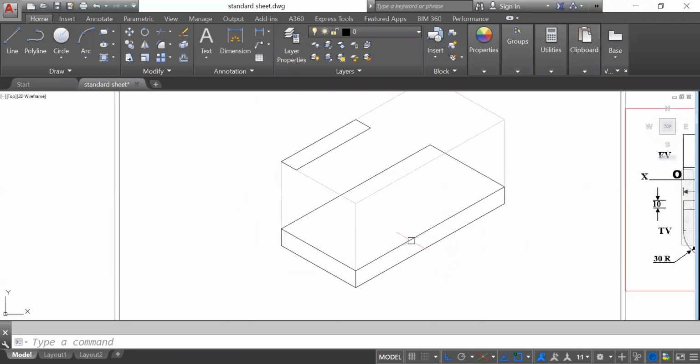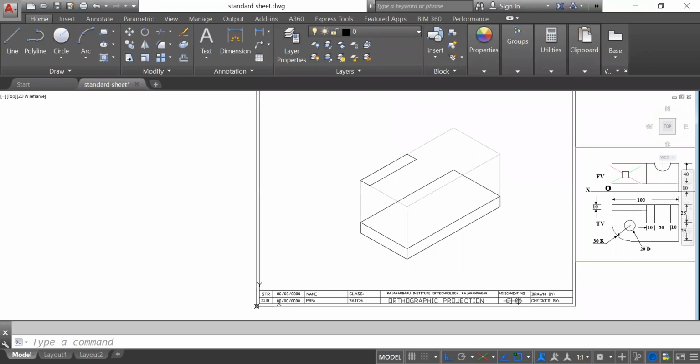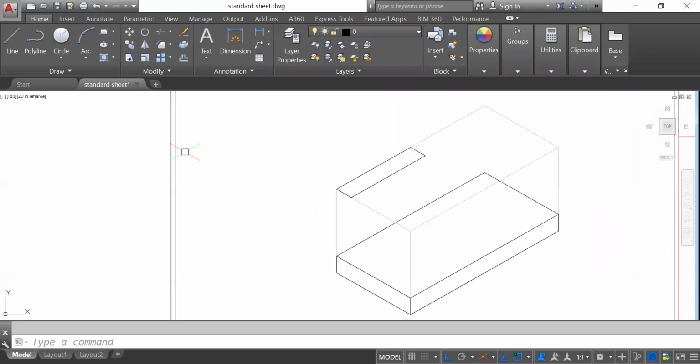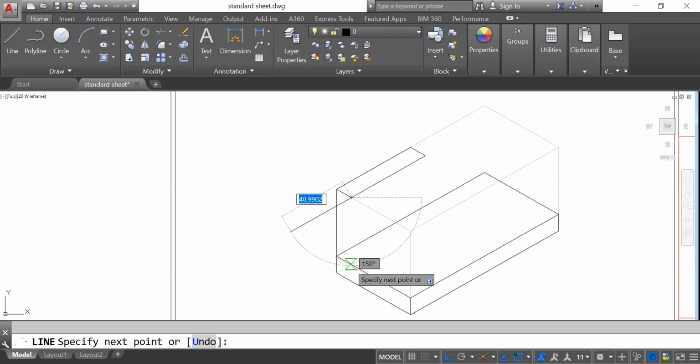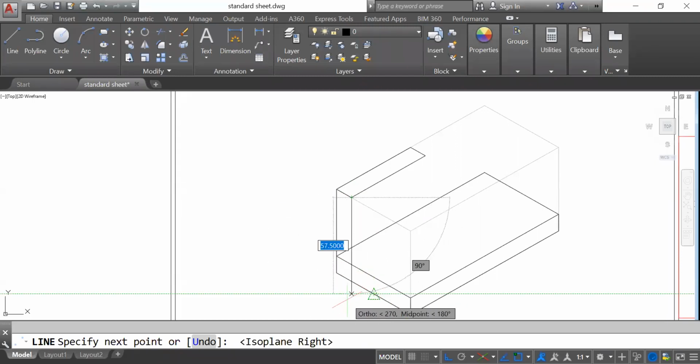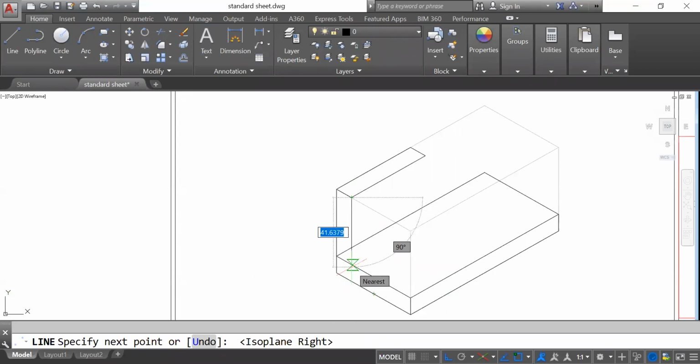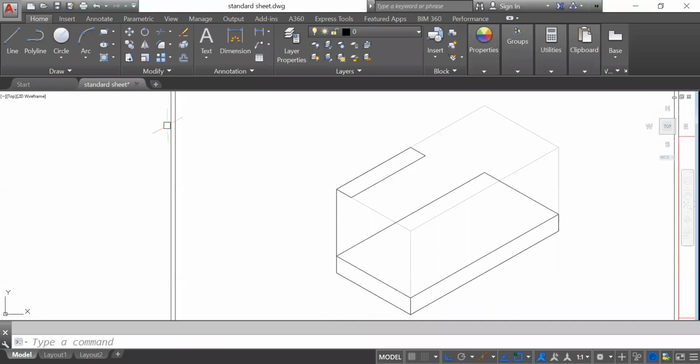Okay. Now we have to give the thickness to this because it is throughout. If you observe from the front, it would be a rectangle. So we have to give the thickness. So slowly select the corners. Always look into the corners. From the corner, you will get all the drawing here. Okay. So Control E. If it is not matched properly, what you can do, you can create it like this. You can extend it somewhat, and then afterwards you can trim it.